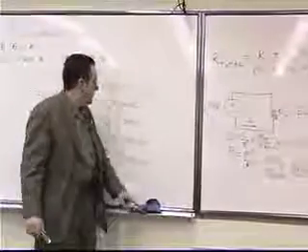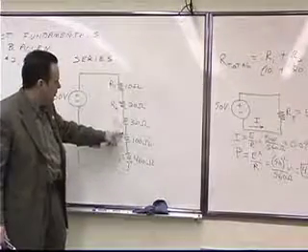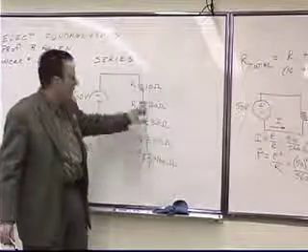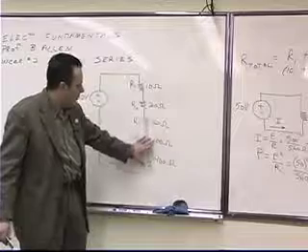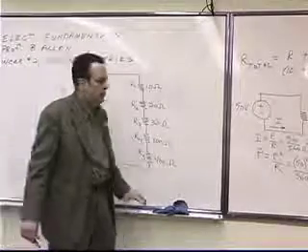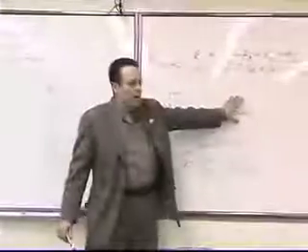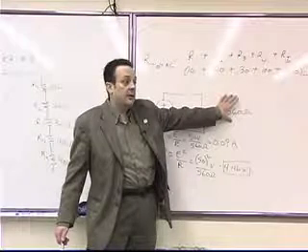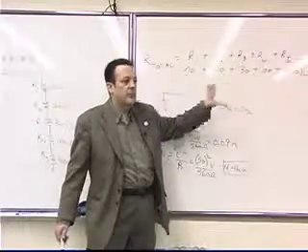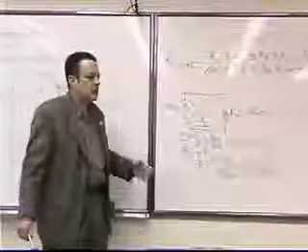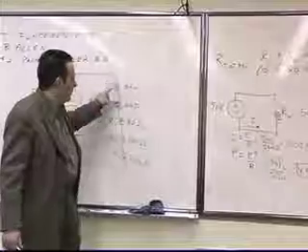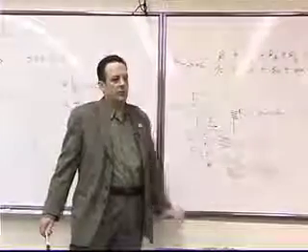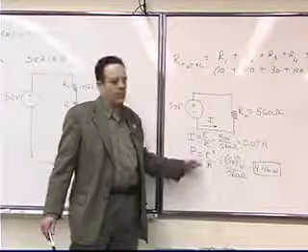if you had a toaster that had 1, 2, 3, 4, 5 elements in it. Because the sum of all of those toaster elements would be equal to an opposition to current flow of 560 ohms and would dissipate that much energy. So you would have to be sure that each individual element wouldn't be overloaded and the toaster as a whole wouldn't be overloaded. So this is a real world application.